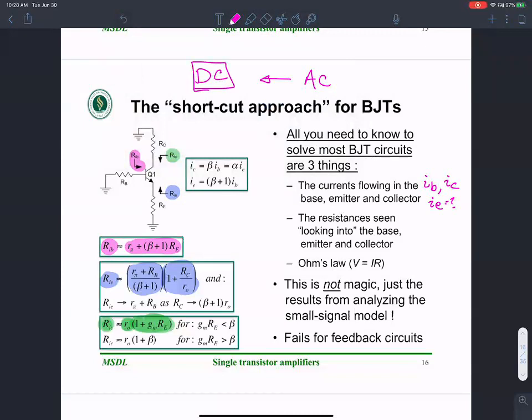And these small signal parameters are important to us in reference to the operating point, or the quiescent point. Then the resistances looking into the base. Once we have these two terms, it's simply a matter of applying Ohm's law. If you want to find out V out, all you have to do is use I out, and I'll show you an example.